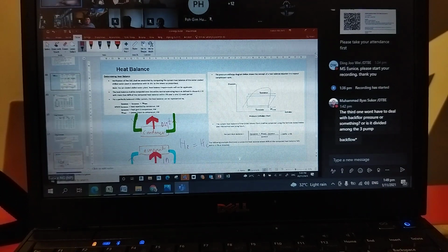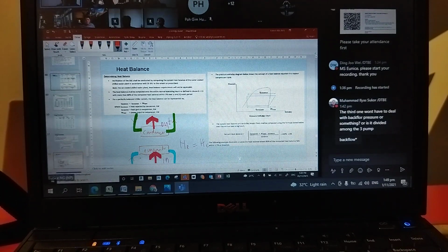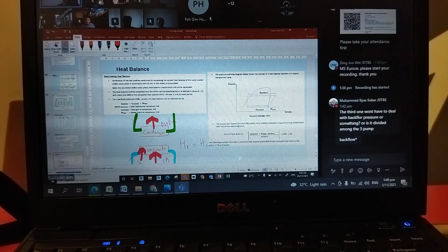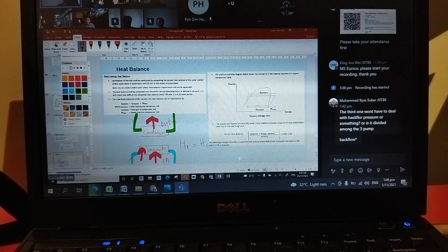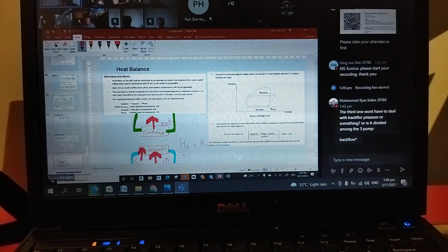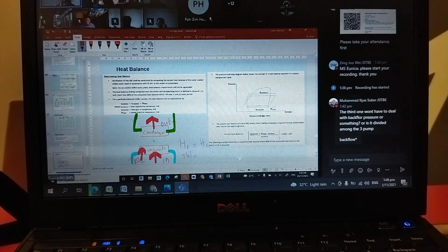But we mustn't forget there's another source of heat: there's a compressor inside, with a motor that produces heat when it's running. So the heat absorbed plus the compressor heat, the W input, must equal the heat that the condenser side must be able to remove.